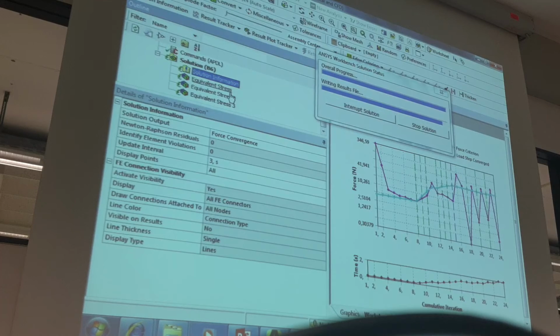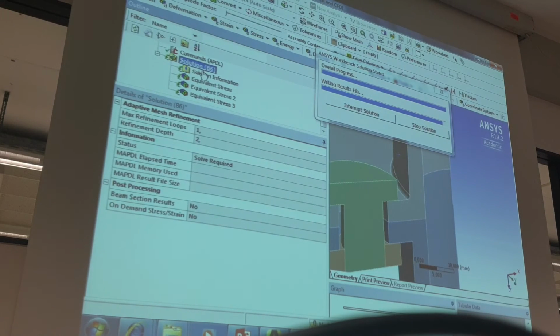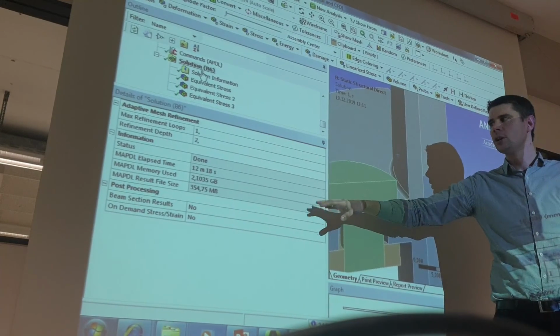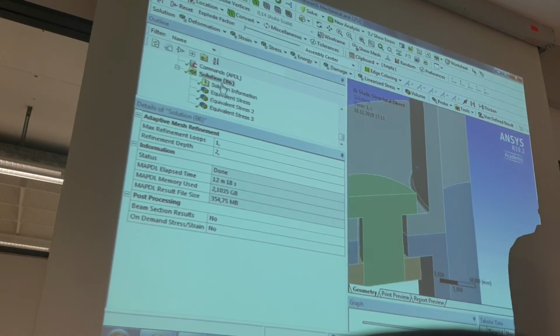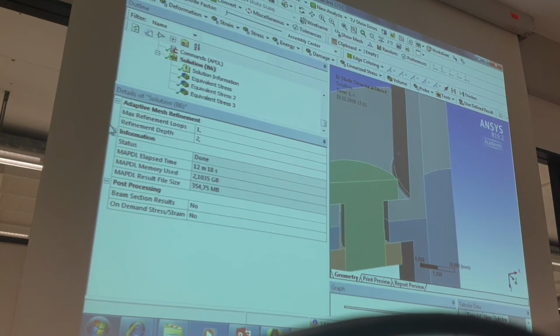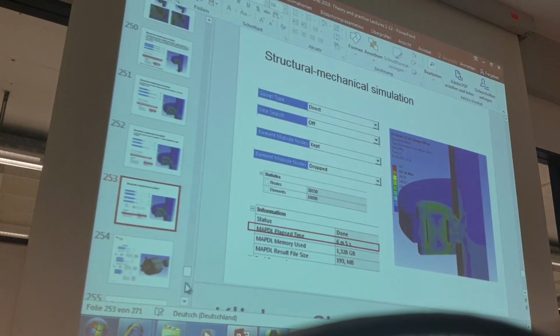Okay, now we finished, and how much time we used for this simulation? This simulation we did, okay, 12 minutes, yes? Do you see it's slow? Maybe tetramesh. Normally, all examples what I showed were with hexamesh, but tetramesh, look, or this example, and maybe in your hexamesh it will be maybe quicker, but now it's slow, yes?